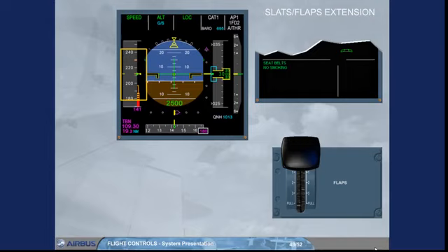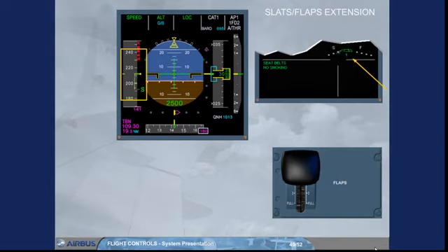When the flaps lever is set to position 1, and as the speed is above 210 knots, only the slats extend to the configuration 1. Then, the speed continues to decrease towards the S symbol. The flaps lever will be set to position 2 when the current speed is lower than the VFE next, relative to the next configuration. Note, in this configuration, if suddenly the speed drops below 100 knots, the flaps will extend automatically to the configuration 1 plus F.